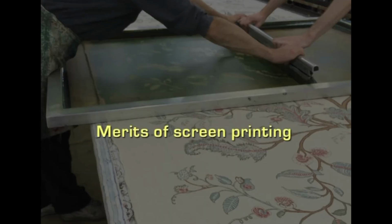Coming to the merits of screen printing, the color can be produced in brighter, cleaner shades than that of roller printing. Designs to be repeated can be much larger and the method is simple to operate and does not require elaborate and expensive equipment. The method enables new patterns to be produced and blotch designs can be printed through this method.